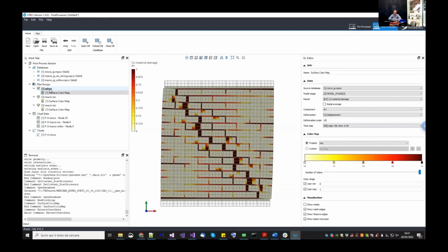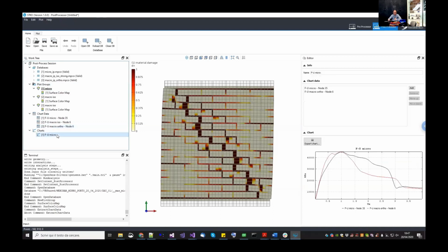So yeah, actually, if you increase the difference between mortar and brick, you will increase the difference here. Because actually, first of all, you don't have to change the material properties of the mortar because they come from an experimental test. Yes, exactly. So it is not that. But let's assume that you have an experimental test where the mortar is, let's say, 10 times even weaker than this one. It will happen that in the micro, it will break even faster. While in the macro model, it is a homogeneous model. So at the end of the day, it is a mix of mortar and brick.